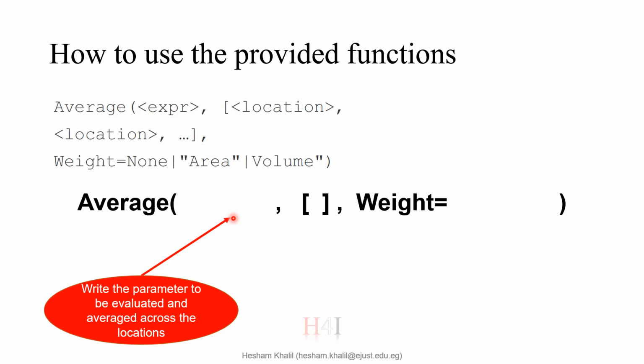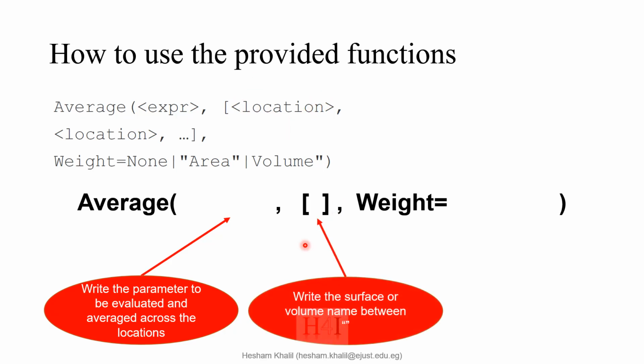Okay. Second thing, here you find the location. Of course, I will write first the square bracket. Then I find these symbols, greater than and smaller than. I remove this altogether. And right here in this location, the location at which I define the average temperature, I use the name of the boundary, inlet, exit, whatever name I used in ANSYS Meshing, which I defined in name selection. I will use it here. But I have to put it between these quotation marks.